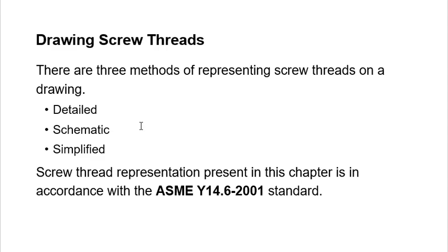So anyways, let's go back to drawing. We come into screw threads drawing. How are we going to do it? Let's take a look at it. When we draw, we're going to draw in detail. We're going to do it schematically and then a simplified version. 3 ways you can do it. And we're going to follow the ASME Y14.6, okay? If you get about this much, I'll be very happy. ASME Y14.5, you should get it by now, Y14.6, yeah? If you don't remember, at least if you remember 14, that's cool.